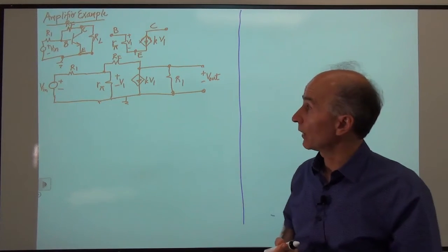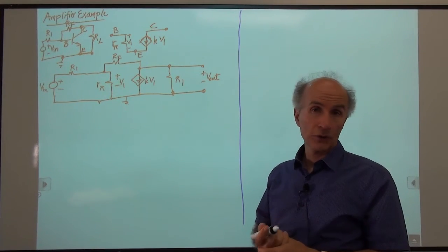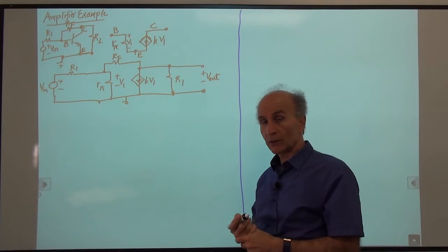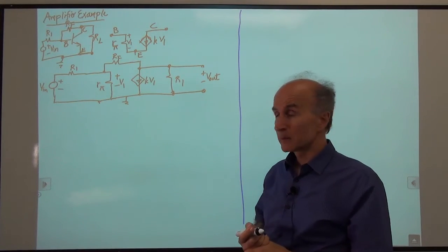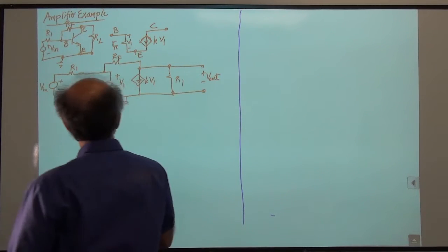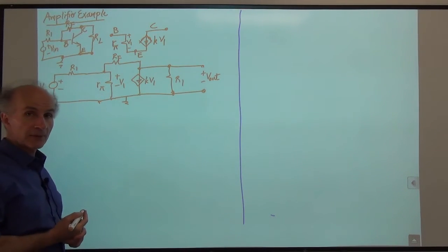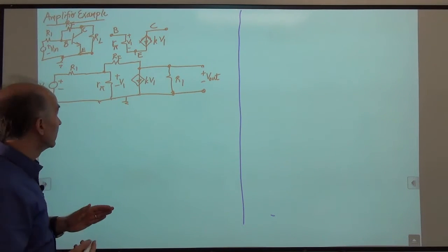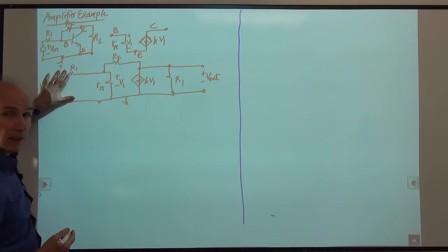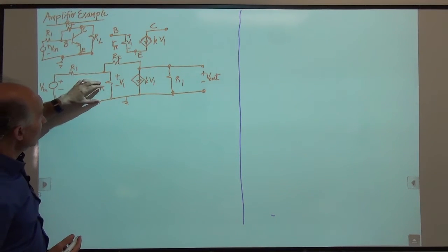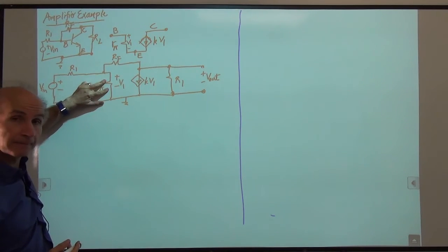Alternatively, we can try to find a Norton equivalent maybe. So where should I pick the Norton equivalent? Okay, well, I am looking for only two wires coming out from section A to section B. So section A can be just this. That's not very useful. That's just the Thevenin equivalent. Section A can include R pi.